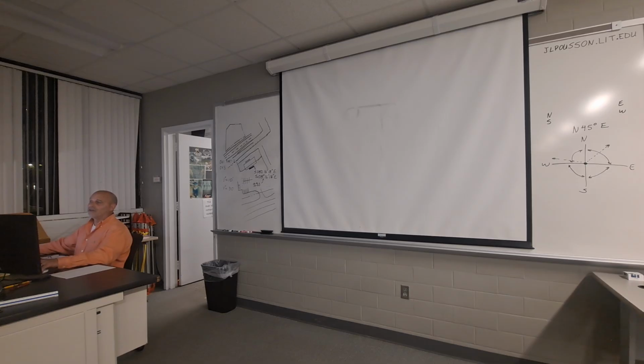You'll still be doing the text 3/32 or 5/32. So your measurements around the outside, we'll talk more about labeling it, your legend and stuff like that next week. But don't forget your two standard text heights, 3/32 and 5/32. That does not apply to your title block, by the way. That is 1/8 text. Go figure.